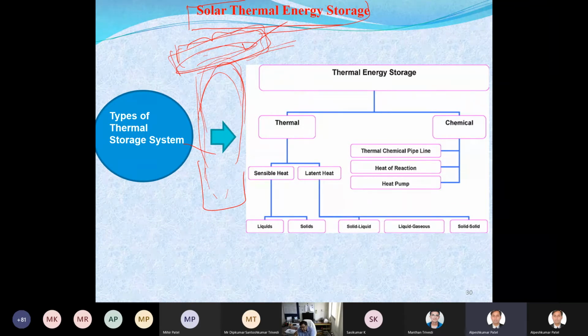So for a solar thermal power plant, storage must be there. I'm talking about that because if you don't have the storage, the plant will be stopped and started frequently. And you know that comparatively, like hydro, it takes a lot of time. So that will be the problem, starting and stopping the plant. Just to bridge that gap or that problem, we need to store the energy or to store the steam, and there are different types of storage out there.